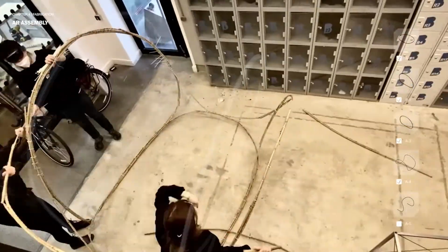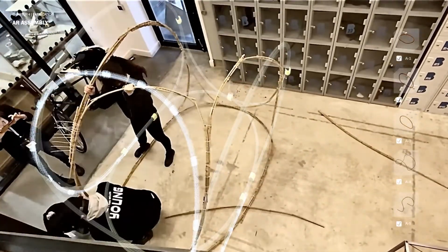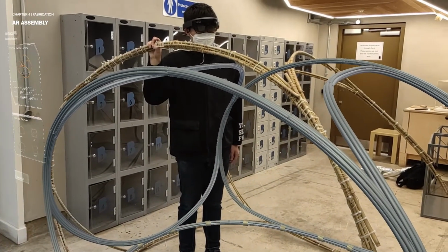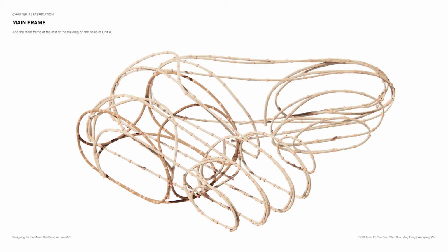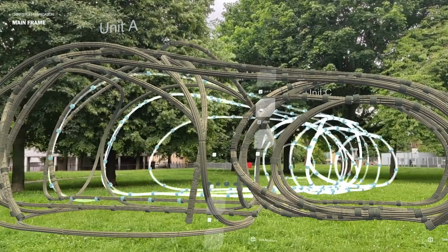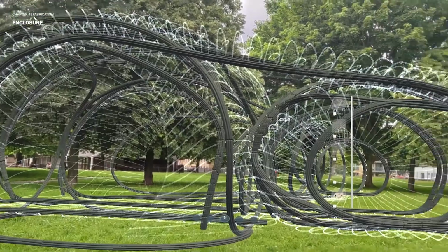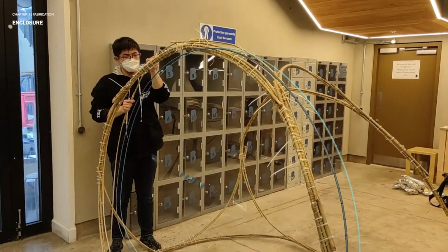As the number of loops increases, the structure becomes more stable and can form the shape of a space which can be used for residence. Different types of joints are used for connecting different layers of components. After the main frame of the living room is built, we assemble the structures of the rest of the building and connect them with the living room. Then, we add a secondary structure and enclosure to the main frame following a similar assembly guideline. We use thinner bamboo poles to assemble the secondary structure.